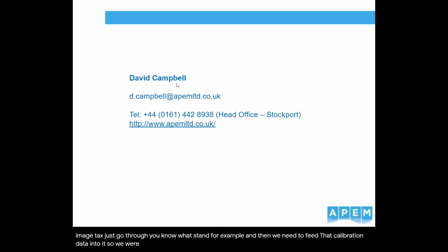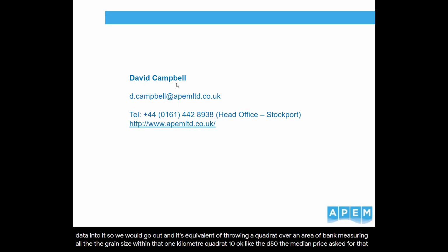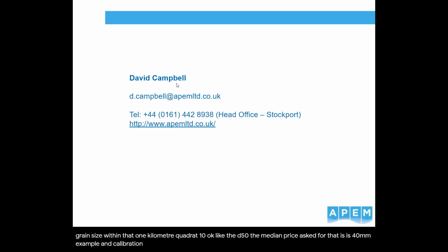So it's the equivalent of throwing a quadrat over an area of bank, measuring all the grain size within that quadrat, and saying, okay, the D50, the median grain size for that is 40 millimetres, for example, and that's a calibration point. We don't go out physically to the river because we don't need to, because of the resolution from the imagery.